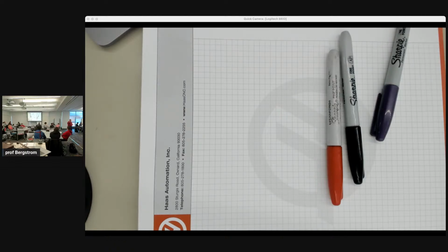So we simulate the cam, set the tool offsets and the work offsets. We used to have a 5-step checklist because I combined the tool and work offsets until we determined that we shouldn't combine those, because you could do one, forget to do the other one, and you wouldn't have a separate check mark to know whether you did the other one. You have to do both. Okay, so what's the next step?